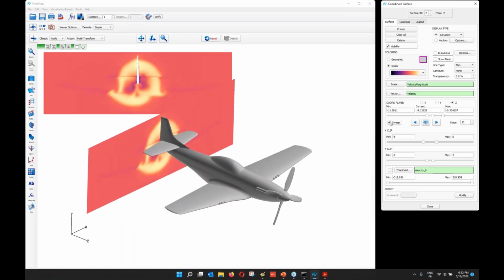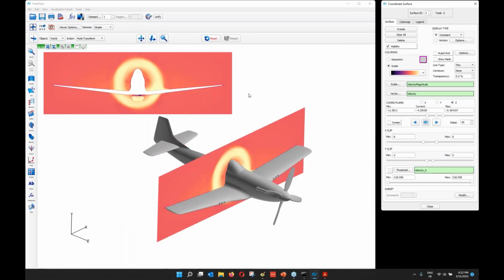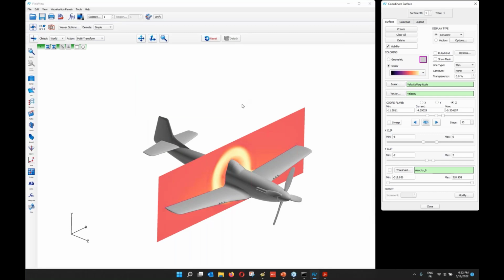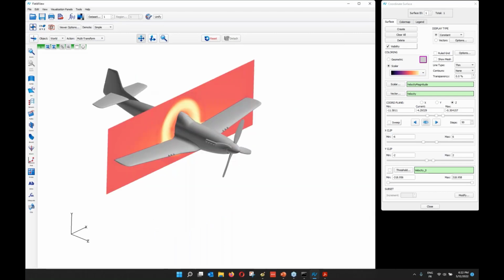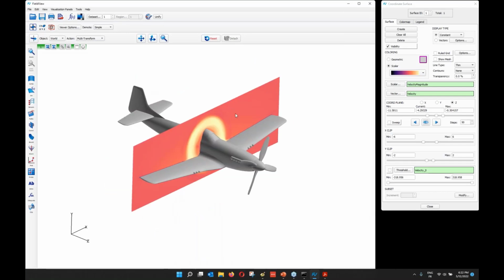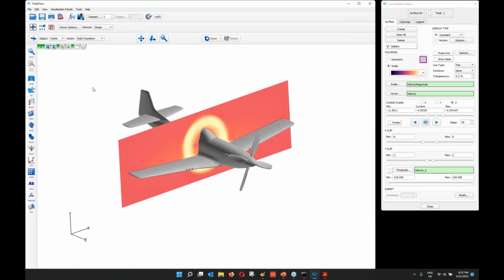Okay, let's get rid of the one I have on the side over here, and I'll show you another way to do something a bit similar, this time working with multiple windows. FieldView has the ability to cut that graphic window, and as you do so, you can define what you're putting in that new window. It's made with those buttons over here that show you the direction of the split. So we're going to split vertically. And I'll start with the instance.